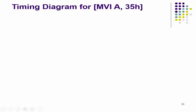Next example, that is MVI A, 35 hex. The typical instruction format you know very well consists of an opcode field and an operand field. If we put this particular instruction in that format, in the opcode field you will find the opcode for this MVI A, and in the operand field we are going to consider this 8-bit immediate data. So MVI A means move the 8-bit immediate data, that is 35 hex, into the accumulator.